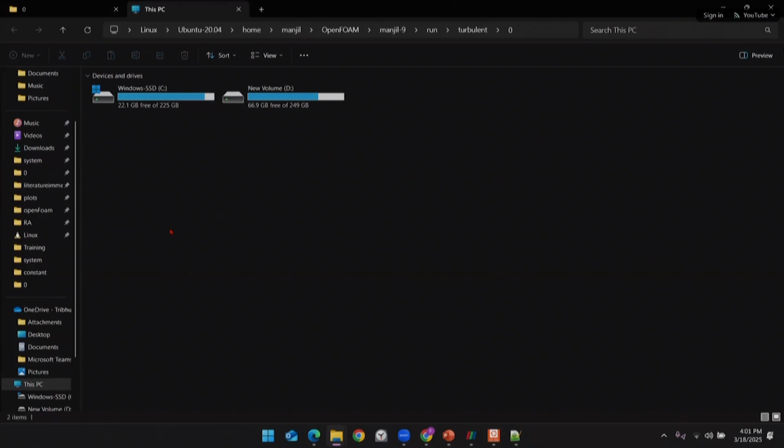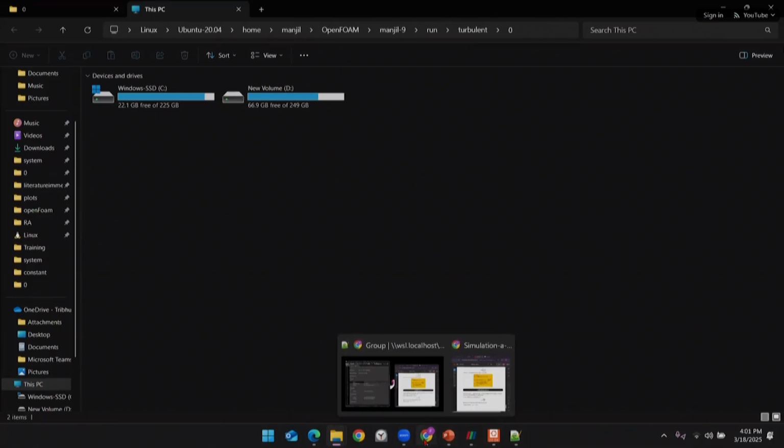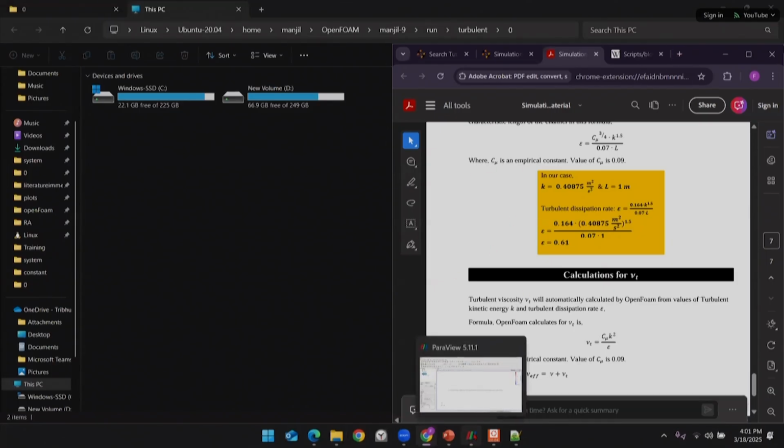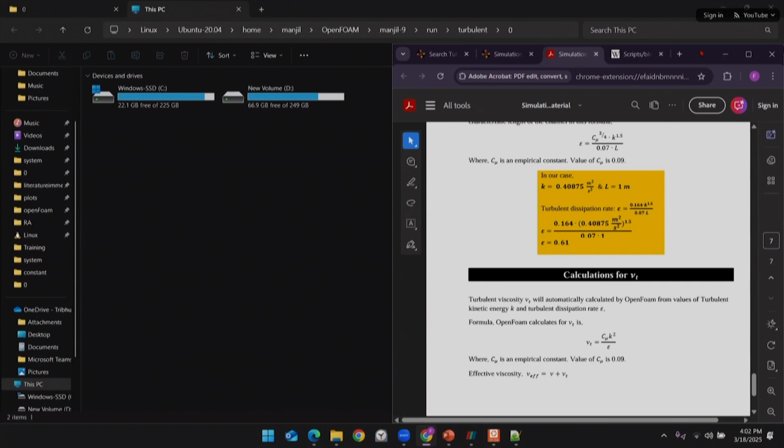Just one question. In the outlet region there is no end effect, which is why it is zero gradient over there, with no value in the outlet region. Can you tell me the physics at the outlet? Actually, the zero gradient boundary condition doesn't calculate on the boundary, but takes the value from the internal cell, that is, the cells near the boundary. So when you solve these equations, the gradient is zero in that part.